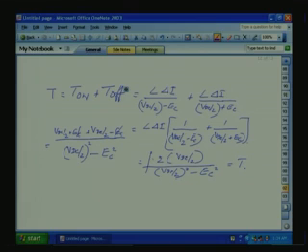Okay. We got T. Once T is known, we can find out the switching frequency, that is our PWM frequency. So, what is the PWM frequency here? PWM frequency F is equal to 1 by T. Here we have to put the L delta I, which we have missed. So, L delta I is also there.